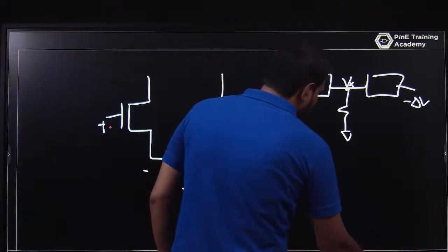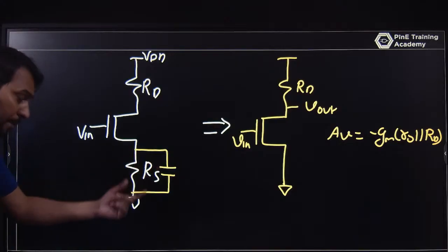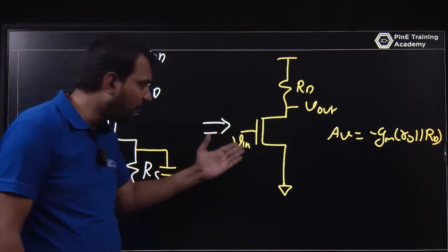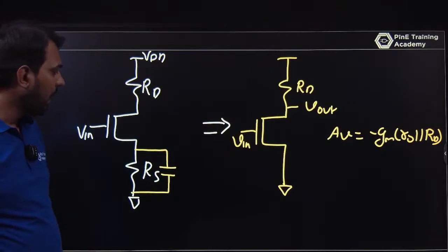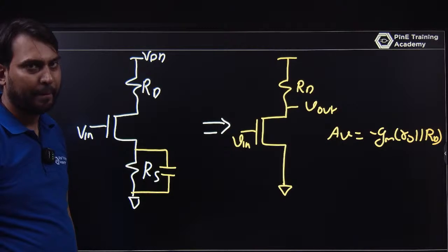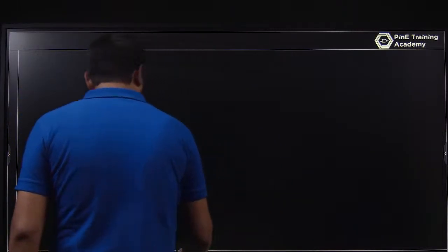So we will use this concept. Here I can use one bypass capacitance, because with the bypass capacitor at that frequency this capacitance acts like a short circuit. In a DC bias this capacitance acts like an open circuit. Okay. Let's talk about the input impedance and output impedance.